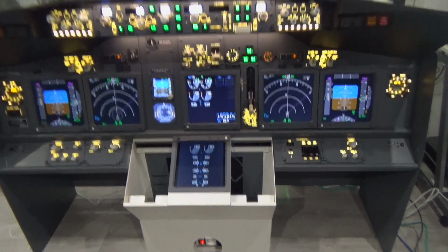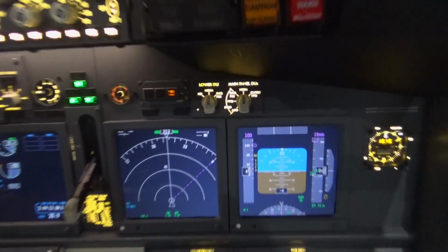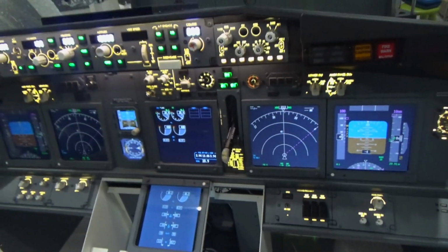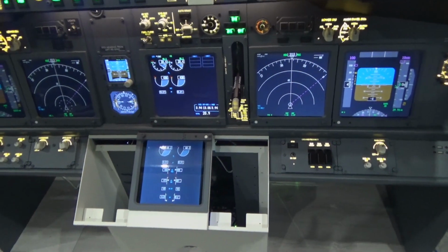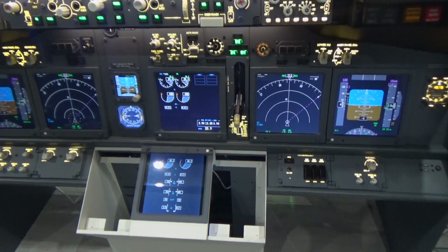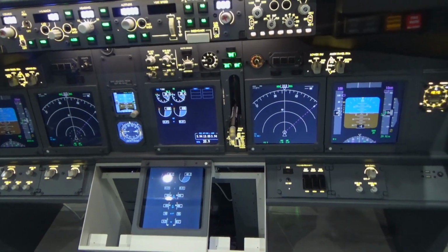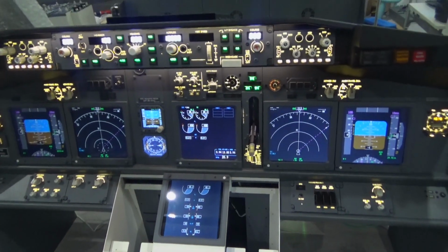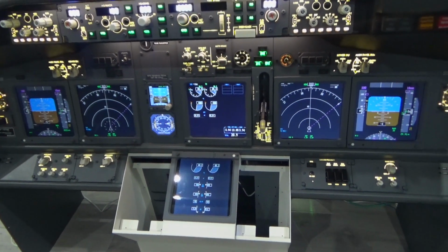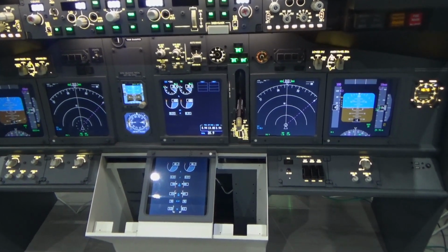Now, I don't have the EFIS. I don't have the two CDUs. I do have them, but did not connect them. And of course, you're going to have some sort of FMC issue there, because it's trying to communicate with the FMC but not finding it. One thing for sure is that when you test these modules one by one, you can probably only test 70-80%. You cannot test absolutely everything, because you need to connect the rest. Otherwise, you have to simulate using the ProSim display that I showed you before. But otherwise, you can only test up to a certain point.